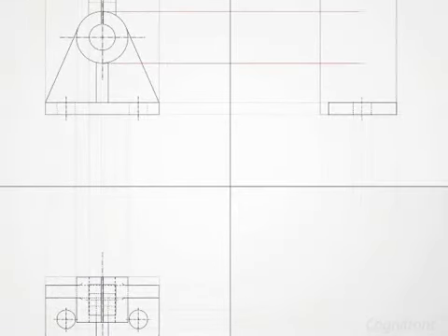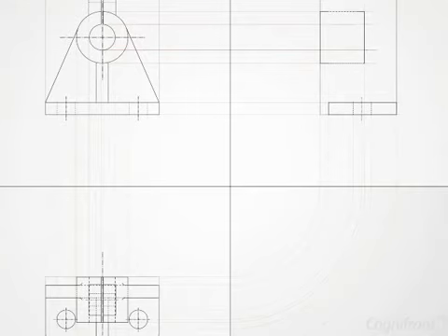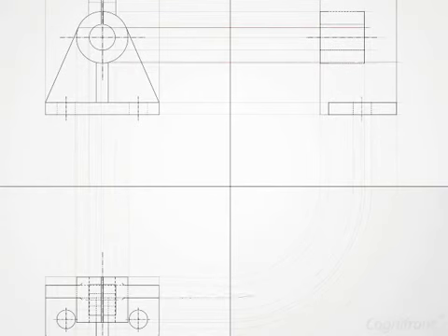Let us now draw the rectangle of the cylinder. The cylinder has a hole, so its dotted lines are visible. Observe that we have dotted center line for this hole. Then generate ribs connecting base plate and the cylinder.